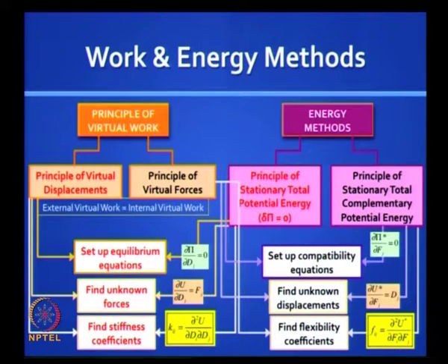You use this to find some unknown displacements in the displacement field. So instead of setting up equilibrium equations, you now set up compatibility equations. Instead of finding unknown forces, you find unknown displacements. Instead of finding stiffness coefficients, you find flexibility coefficients. You are doing a similar exercise and you see a beautiful symmetry in these relationships, and you can do the same thing using work methods without getting into energy, and that would be a use of the principle of virtual forces.